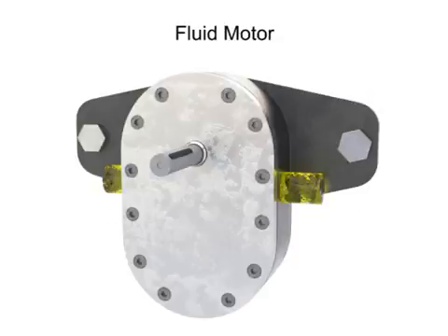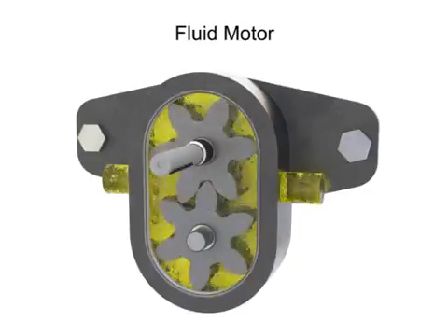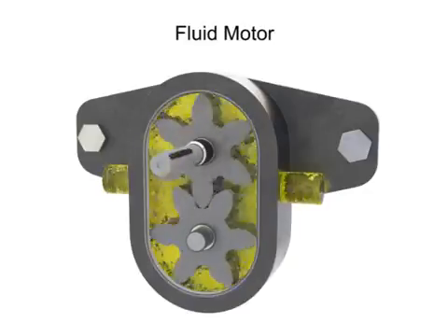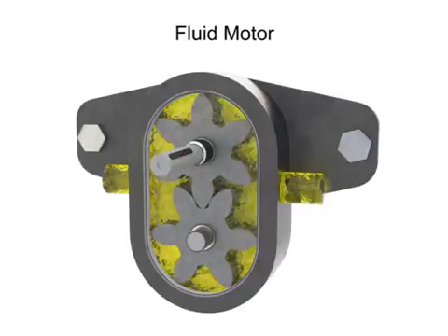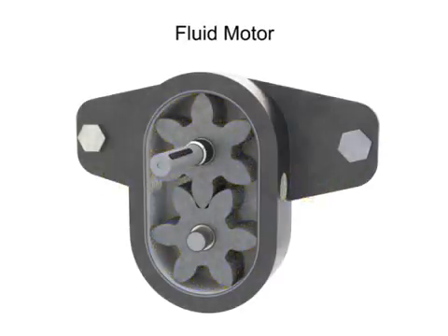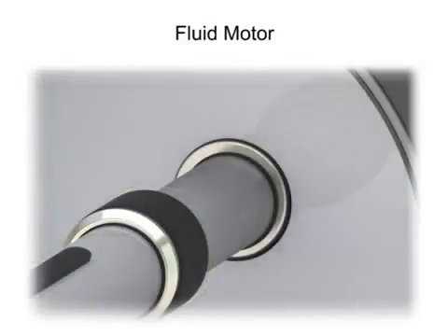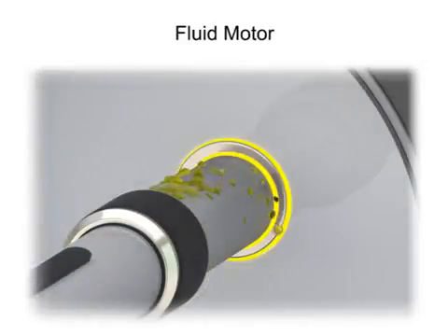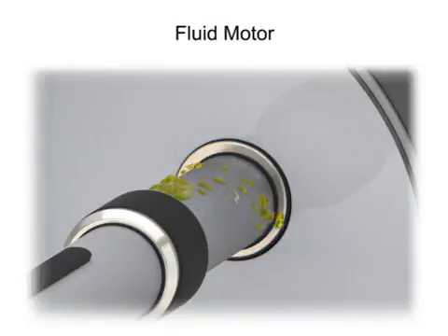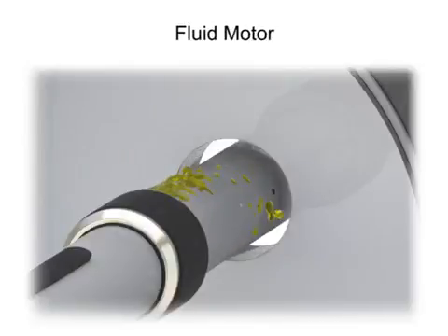On most fluid motor applications, it's necessary to have a motor which can accept high pressure on either port so that the motor can be reversed. In all hydraulic devices, a small part of the high-pressure oil will slip through clearances between the gear sides and the housing and will collect in the seal and bearing pockets. If not vented, these pockets would soon be exposed to the same high fluid pressure as the ports, which can then dislodge the shaft seal. To prevent this from happening, several motor construction methods are used.